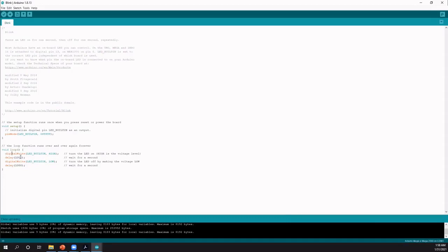Now, if you want to make this a little bit more interesting, you can play with the timing of that blink just to see how that looks. So for example, let's say I make the LED turn on only for 100 milliseconds and then I turn it off for 200 milliseconds, something like that. If I upload this, I'll switch over cameras before changing it so you can see the difference.